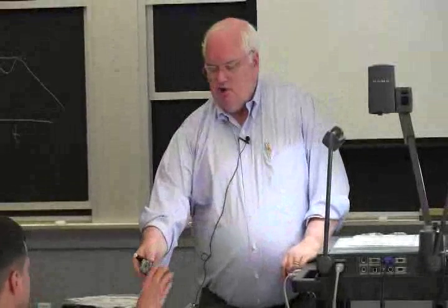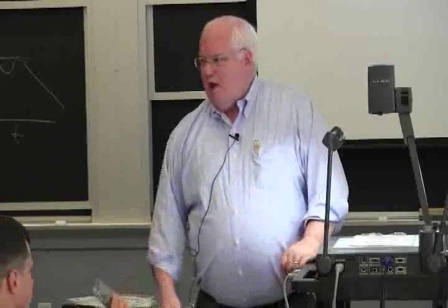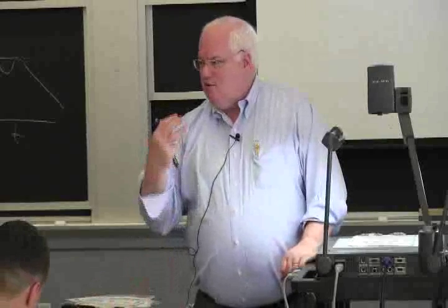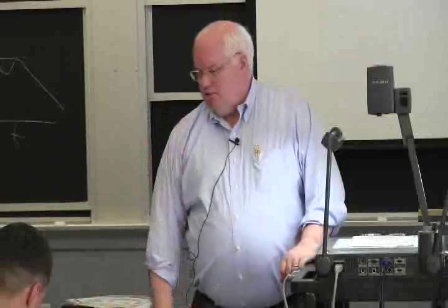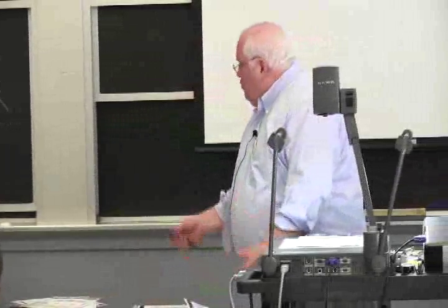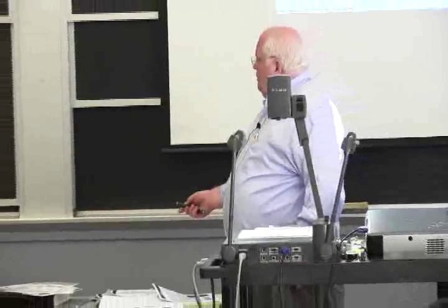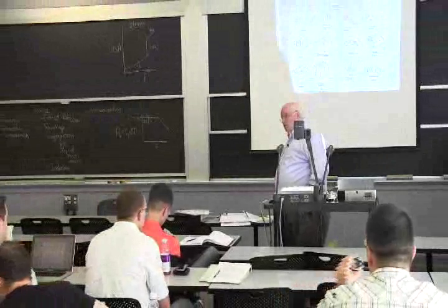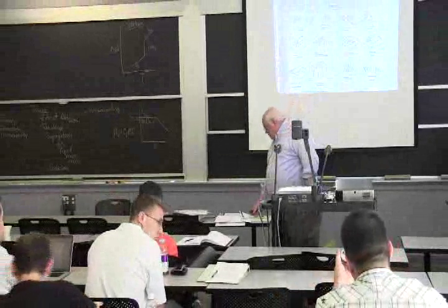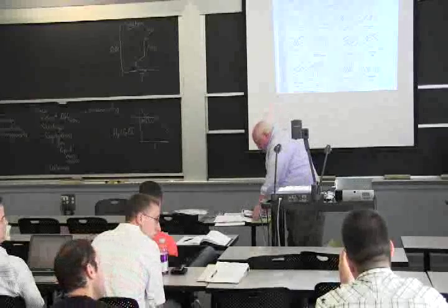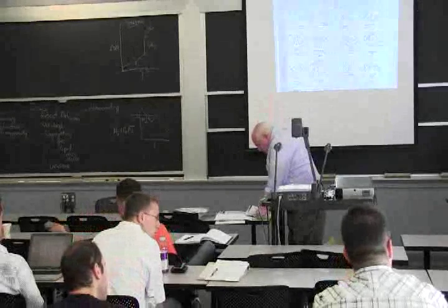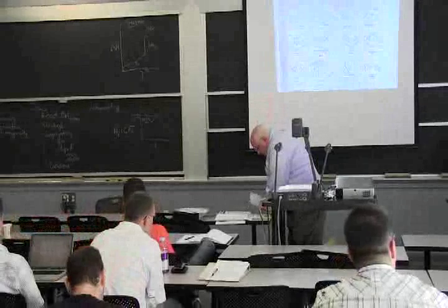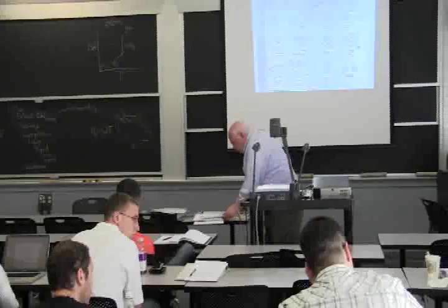I just got this because you look at it, someone just broke it with a hammer and you can see the columnar grains from the metal mold, okay? So the way you extract the heat will determine the structure of your steel or your metal, whatever type of metal it is.